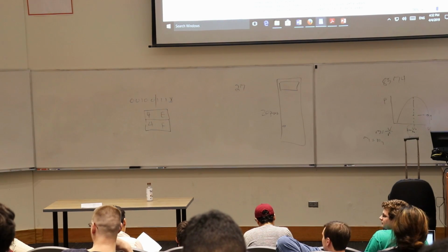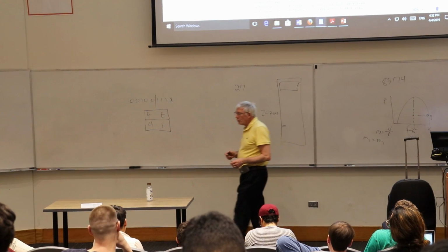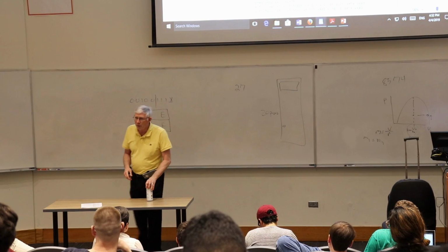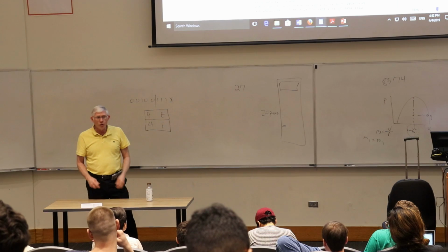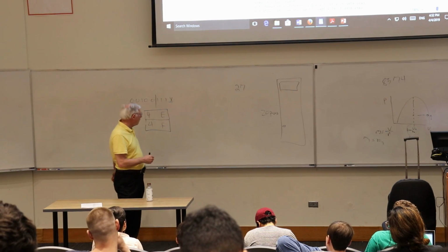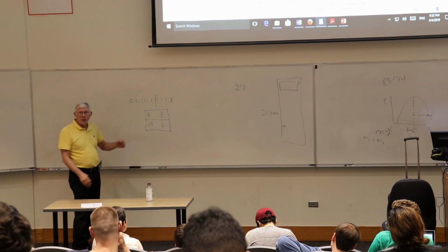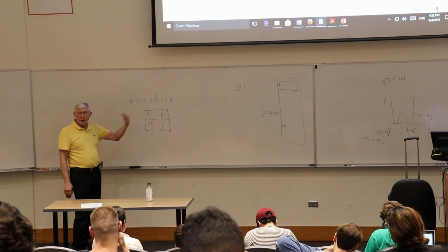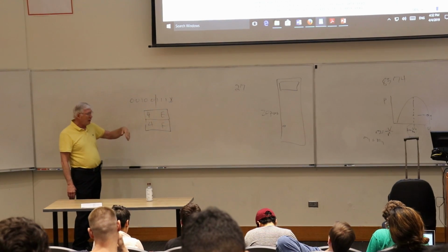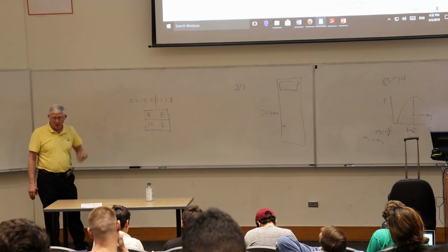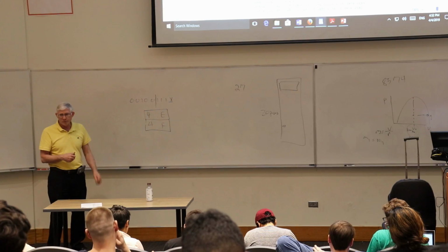Yeah? So can I2C ever be full duplex, or is it always half duplex? It's never full duplex. It's always sending information one way or the other. And usually because you have a master-slave relationship, the master always has to send out the slave address, and then it can do multiple reads. But it has to first send out a slave address with a read bit appended, and then the slave knows it's supposed to keep reading. And usually they're set up so if you keep reading, it'll keep sending you information.